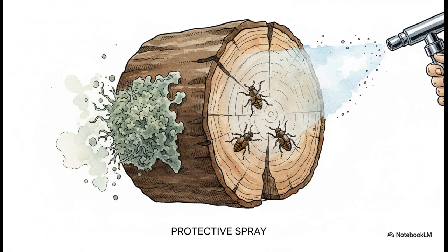The third type is organic preservatives. These are advanced natural or chemical formulas designed to fight off a dual threat, fungi and insects. You see, the two are actually linked. Fungi, like mold, softens up the wood's cells, which makes it super easy for bugs to bore in and eat it. By stopping the fungi, organic treatments essentially eliminate the insect threat too.